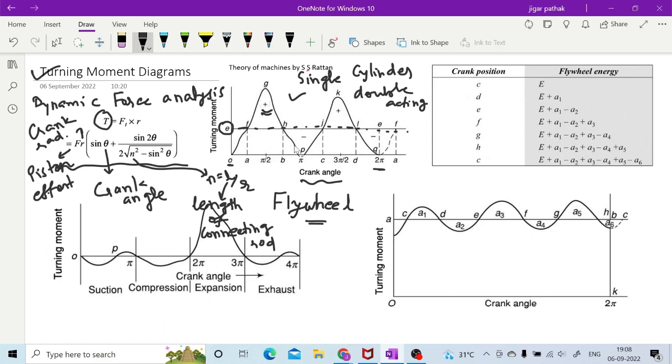And whenever the energy generation is less, here energy generation is actually this much only, right, but the required is this also, right, over here, which is mentioned in negative, this is also required, right. So when you are having a flywheel in your mechanism, what will happen is that flywheel is going to provide this required energy during this particular motion, while here it will store this energy because it is in excess, right. So this is how your flywheel is going to work.